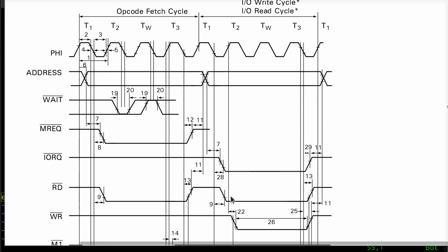Whenever these both go active at the same time, I'm going to say the next state will be 1 after this falling edge. Now my logic will be, if the state is 0, which happens all the time, except for when it's in state 1, which it goes into when this edge here falls.